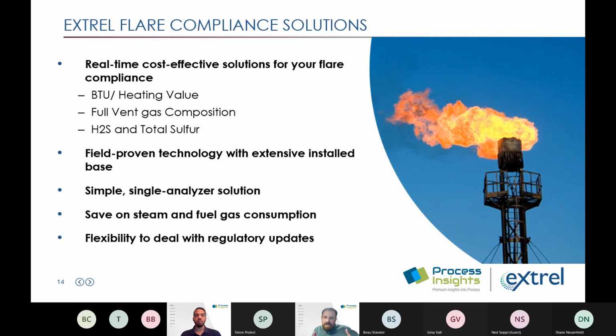Okay, so that was kind of a quick introduction, but I think we were able to cover what the flare gas mass spec is and why it is being used on flares. We talked about the fact that the mass spec is a single analyzer for measuring everything within that stream and covering all of the required parameters: BTU, total sulfur, H2S, flare control in real time, as well as the full speciated analysis. Basically, nothing's going to measure as much in the sample or do it as fast as the mass spec.